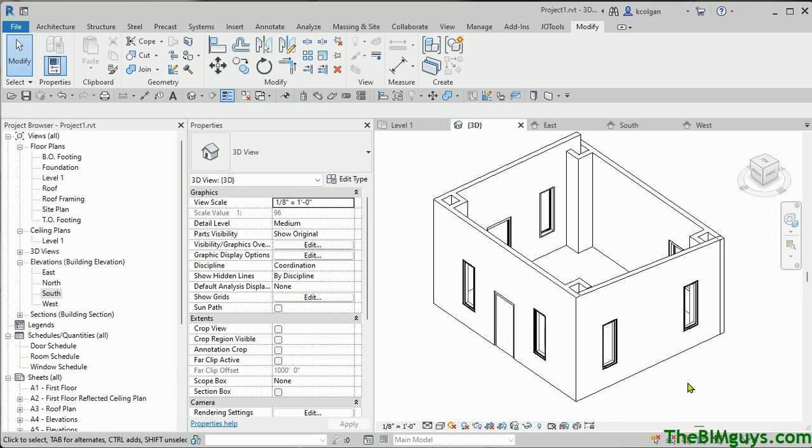This week we're going to talk about adding a top plate or a sweep to an existing or new wall. Sometimes you have walls that have some weird things going on. Like for instance, this is coming over here, I've got some weird connection here, I have a slope here. How can I have something trace along the face of that element? Now you can use what's called an embedded wall sweep, and that would work to place it here.